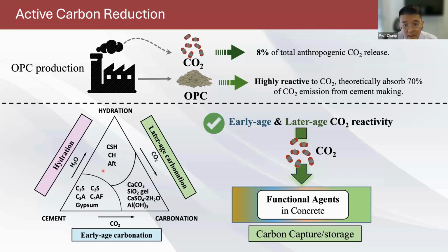So all those equations and the chemical features of cement make it possible for CO2 to work as different functional agents in concrete using the early age and later age CO2 reactivity. Later age means even demolished, used concrete can have this carbonation reactivity, so that carbon can be captured and stored.